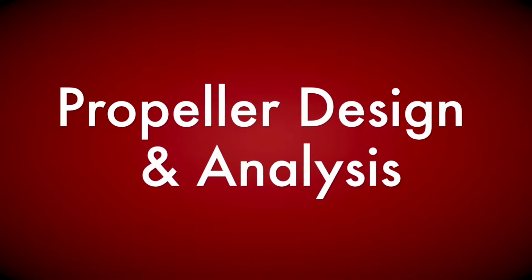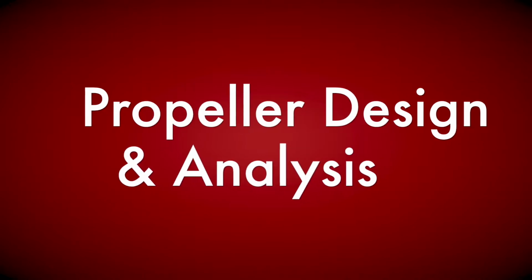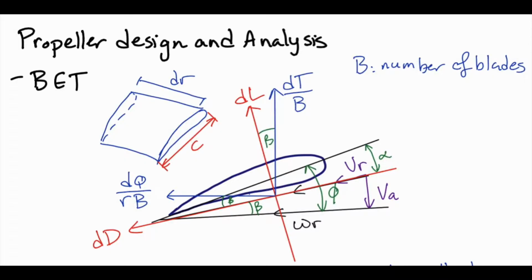So how can we design propellers and analyze them? One way to do that is by using blade element theory. Blade element theory analyzes the performance of propellers by taking 2D sections at different points on the propeller and analyzing the section independently. By doing that, we end up with an airfoil section of chord length C, which corresponds to the chord length of the propeller at this point. This airfoil is subjected to the incoming flow velocity VA and the radial flow component omega r, where omega is the rotational speed in radians per second.